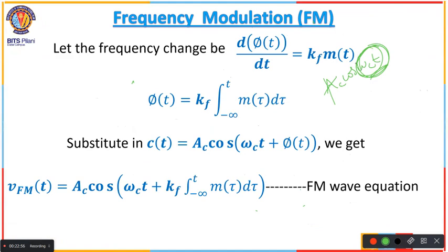And this frequency of the carrier wave, now we are varying according to the instantaneous message signal, right? Now let us play with only this. So I am going to consider this as theta of t. This omega ct, I will make it omega ct plus phi of t. That is going to be theta of t. Have you understood this?